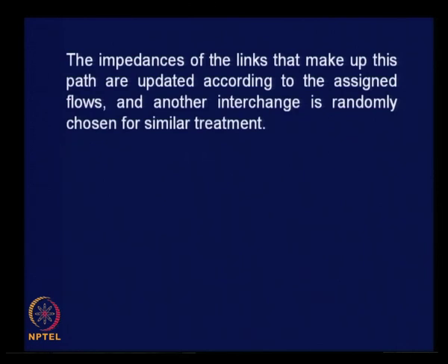So we must have some increased travel impedance; travel time would have increased for subsequent assignments, right. Since we have a relationship between traffic volume and speed, after having known the assigned traffic you can find out what will be the resultant speed on each of these links after the first stage of assignment. So knowing the speed you find out the travel time implication and take that as the revised impedance for those links which were involved in the first step, right.